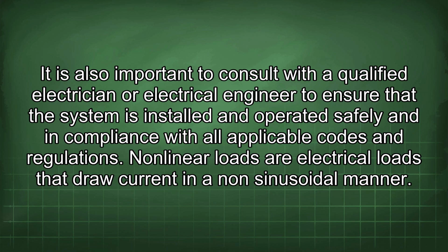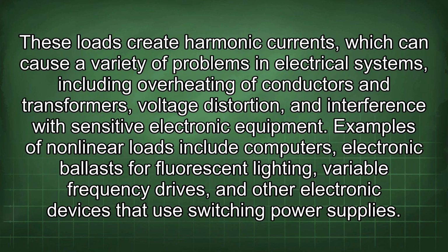Nonlinear loads are electrical loads that draw current in a non-sinusoidal manner. These loads create harmonic currents, which can cause a variety of problems in electrical systems, including overheating of conductors and transformers, voltage distortion, and interference with sensitive electronic equipment.